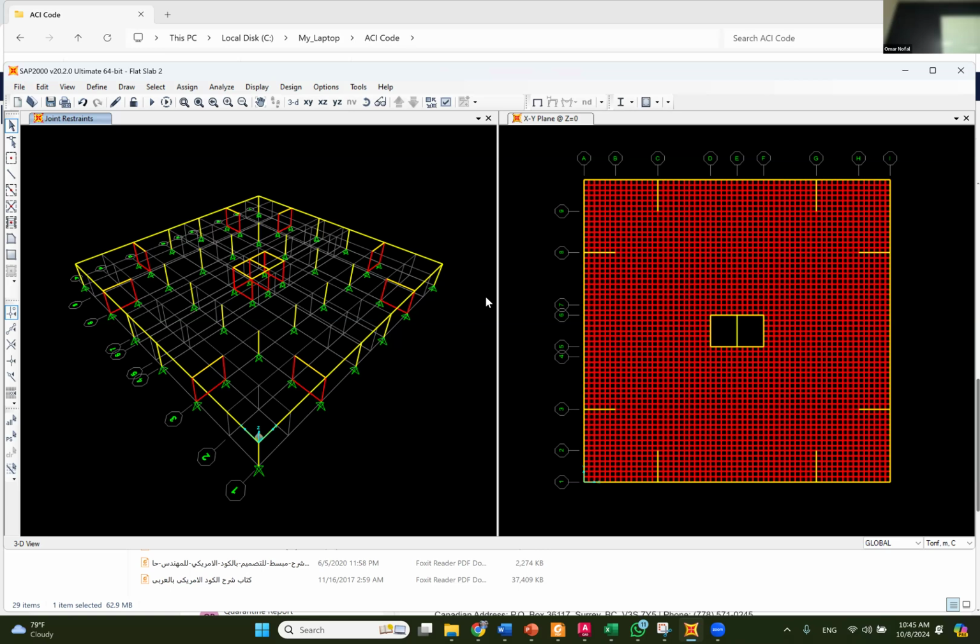Yeah. So besides the size of the shear wall, it's the compressive force and not the lateral force. Well, what do you mean? We are just modeling the geometry. We didn't get to the forces. Yeah, but when we design a shear wall, what is the governing factor for deciding the size? Is it the lateral forces? It's close. We do a preliminary section like the way that we did it now, and then based on the vertical forces we get the dimension, and then the reinforcement.